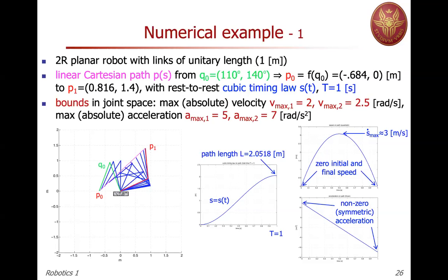So you have everything you need, not just graphically, you have it analytically to compute also the Cartesian acceleration, and then to invert the Cartesian acceleration into a joint acceleration, inverting the Jacobian. You never cross a singularity here, so you can always do the standard inversion, taking into account also the J dot q dot term at the second order level.